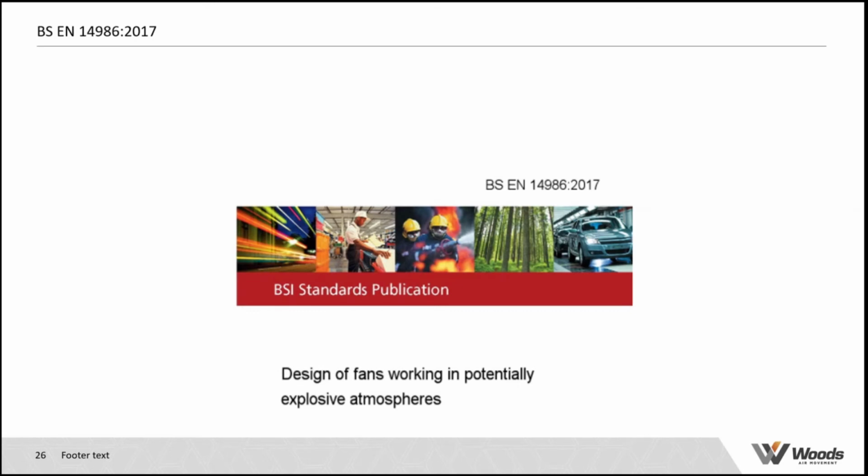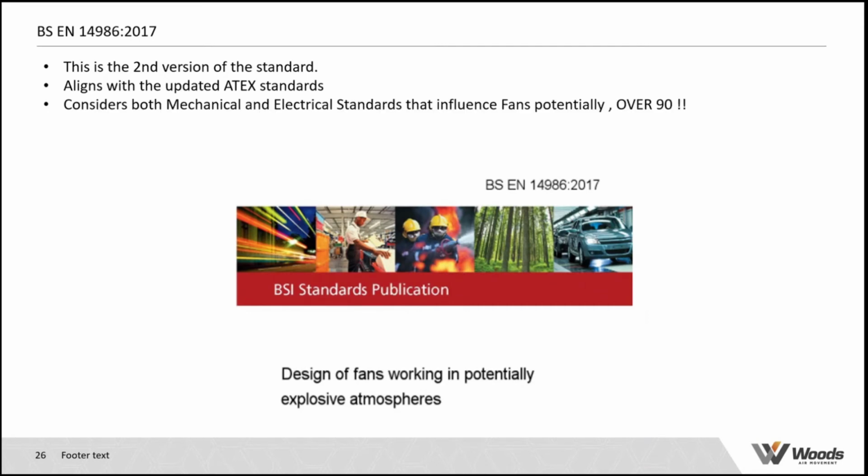So I think it's worth understanding what we do in terms of the way the fans are specified and built. We decided as a company to go the route of using the ATEX specific standard for fans in potentially explosive areas. This is the second edition, and it lines up with the second revision of the ATEX codes and standards.